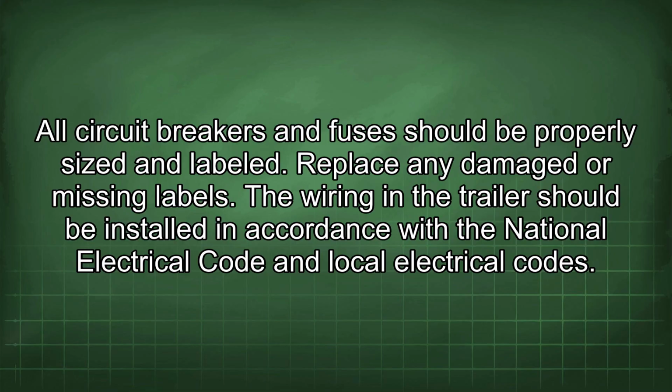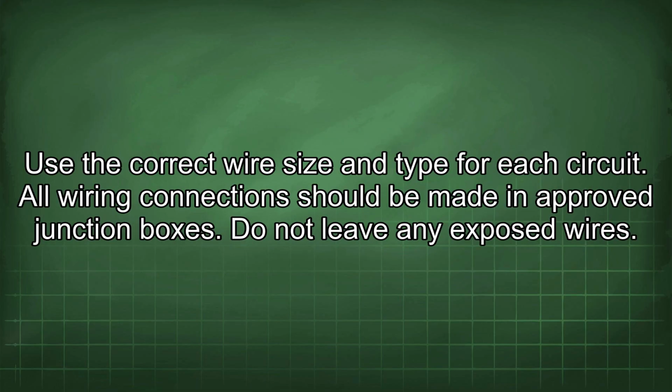The wiring in the trailer should be installed in accordance with the National Electrical Code and local electrical codes. Use the correct wire size and type for each circuit. All wiring connections should be made in approved junction boxes. Do not leave any exposed wires.